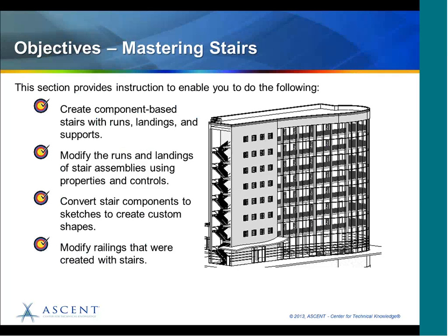We also converted stair components to sketches so we could create custom shapes, and modified railings that were created with stairs. And we applied much of what we learned here to creating a multi-story stair.